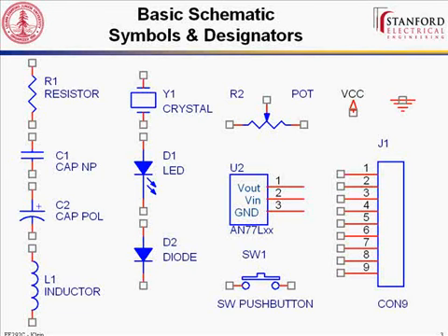So I'll show you later on today, when you have pins that you need to bypass with capacitors, you're trying to supply power to it, you'll need to put a polarized capacitor and a non-polarized one right next to each other. That's the best way to go about it. So non-polarized cap, doesn't matter which way it goes, small values. Polarized cap, it matters which way you put it in, and it's typically for higher values.